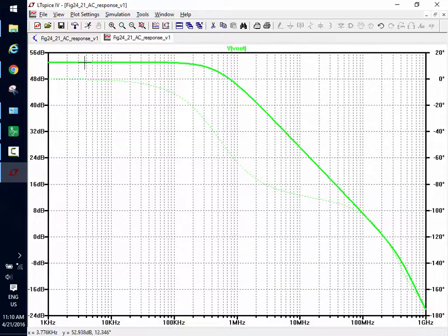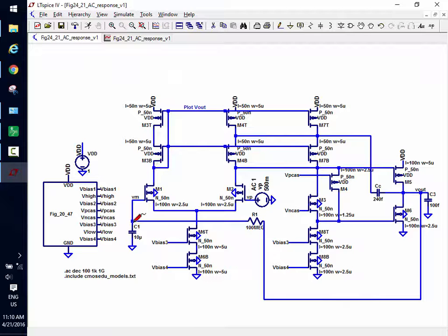The gain isn't that high. Let's make sure everything's biased up properly. 500 millivolts, 500 millivolts. 644. Is that right? Do I want the gate here to be 644? I want it to be a VSG. VSG is 350, so this voltage would be 1 minus 350. Is 644 reasonable? Yeah. What about this voltage before I put my cursor on it? Want it to be 350.